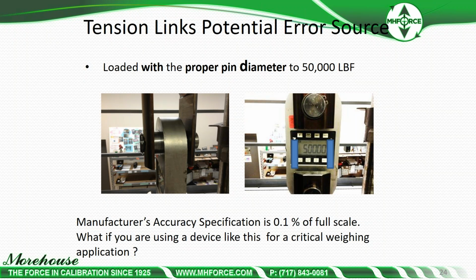Try to use what the customer is using, what they're calibrating with. Try to get those pins and calibrate it with those pins. If you cannot, you need to match the pin size as close as possible. There is a difference between a 1.97 pin and a 2-inch pin.